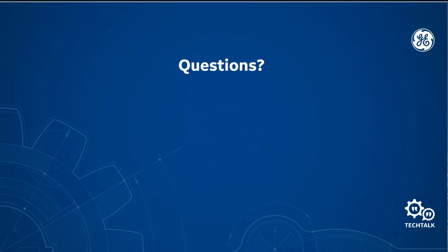Here's another question. How does one calculate and select the correct MOV and stabilizing resistor for high impedance bus differential? As I mentioned in the webinar today, the two different bus differential schemes are high impedance and low impedance bus differential. The high impedance is basically paralleling all the CTs. It's very easy to implement because all you need to do is parallel the CTs. You can support a large number of breakers because it doesn't really matter how many breakers you have as long as they're parallel into one junction point.